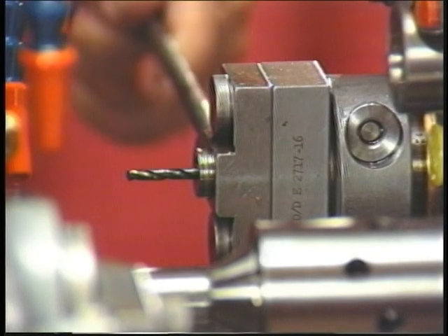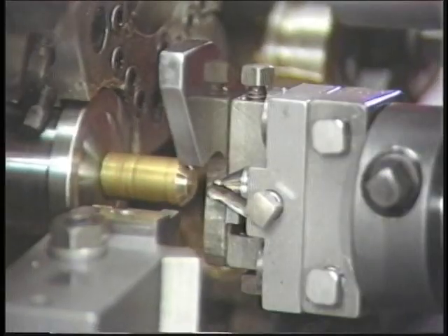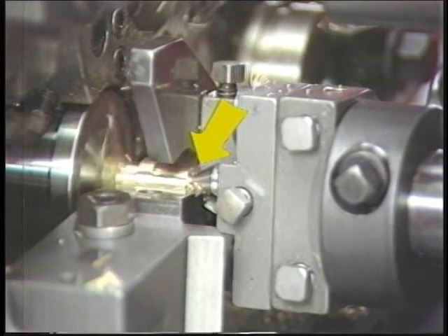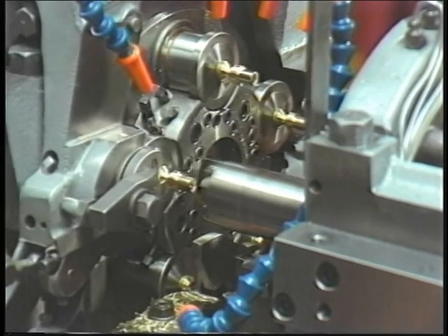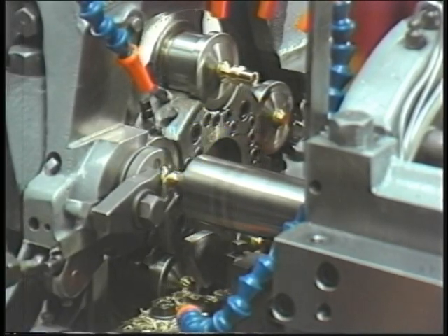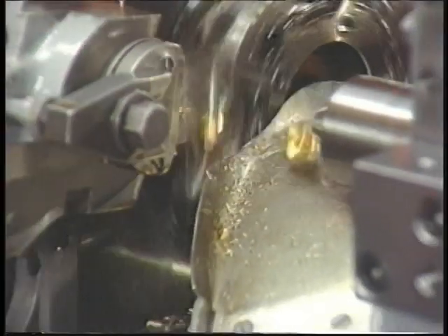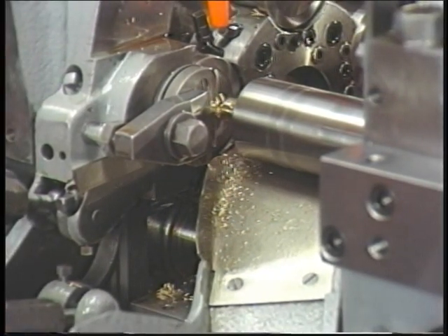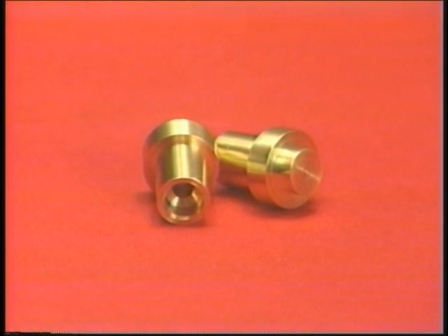Before we discuss tooling itself, you must be aware that the operations of the tools are done in sequence. For example, the first operation of a tool on the stock might be primarily drilling from the tool spindle in the first position. The last operation on the stock normally would be in the 5th position, when the finished workpiece is cut off from the bar of stock and then drops into the work chute. Thus, at the end of a particular sequence of operations of the tools for a specific job, there will be a finished product or workpiece.